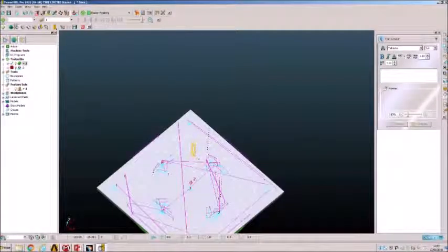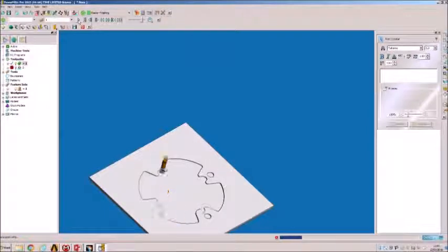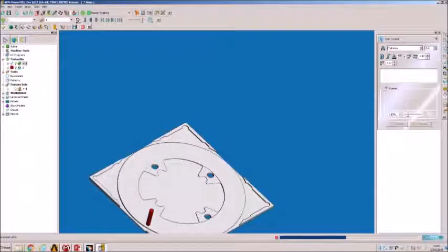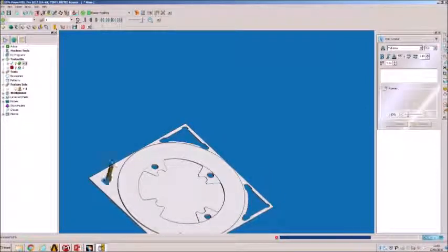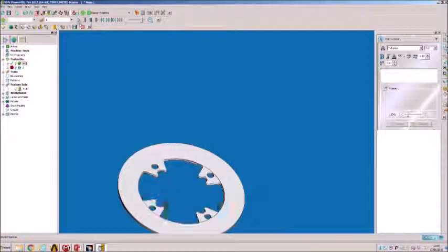The View Simulation toolbar is used to change the toolpath simulation to a 3D block where the machining process can be seen. In this instance, the profile of the disc is generated first. However, as it is a basic 2D shape, it doesn't matter which order the machining process is, whether that is the profile or the drilling first.